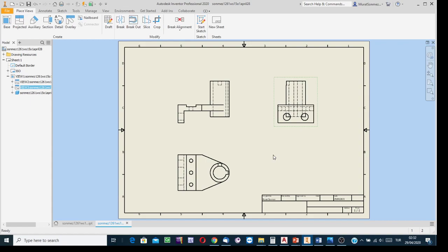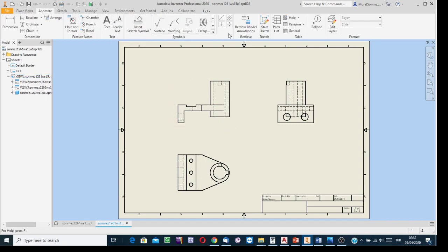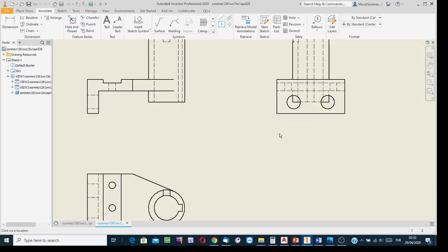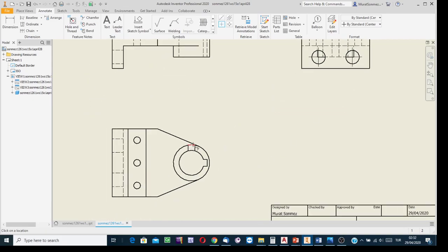Okay? First angle views, first quadrant views. Don't forget to show the axis of symmetry annotation. Okay. If there is a full circle, horizontal and vertical axis, yes. On the left side view, this is a full circle, indicate it has the symmetry axis. This is a full circle, it has the symmetry axis. On the top view, this is a circle, indicate it has the axis.